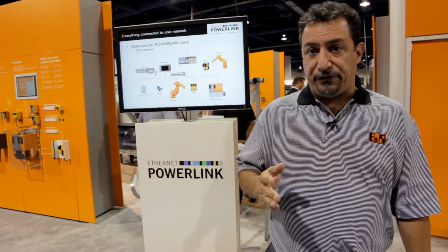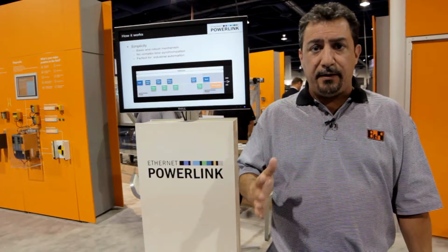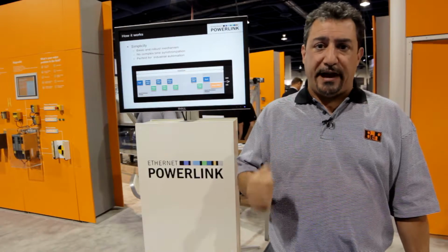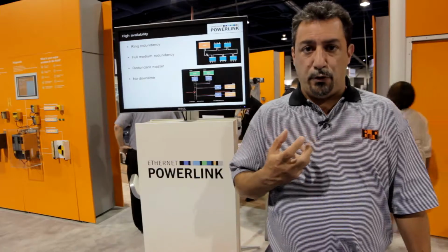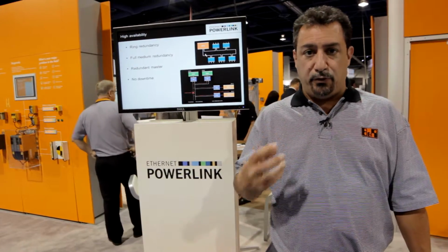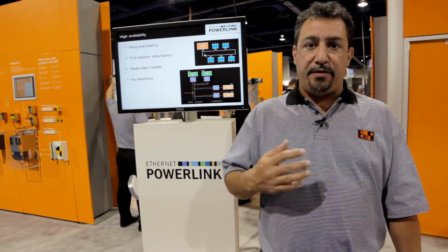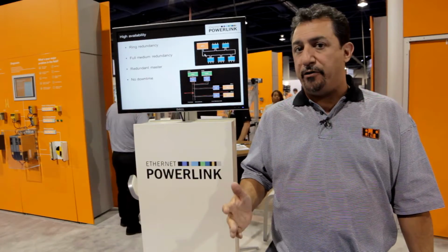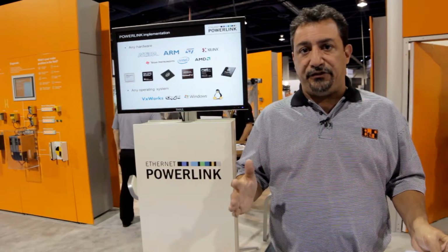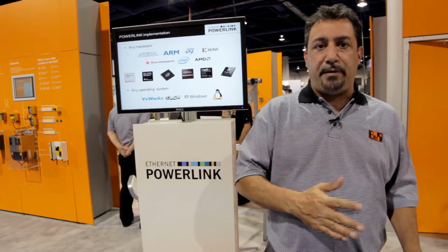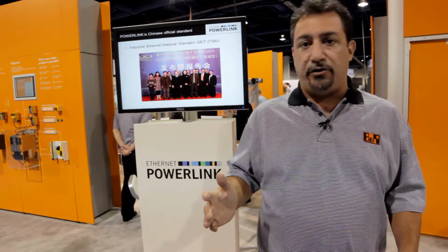The second part of the cycle is where any component can speak, and at that point you can use standard TCP/IP or SNMP or any other protocol. So components on the network are able to publish their status, error messages, etc., that are not critical to the real-time behavior of the system. Because of this division within the cycle, you're able to get real-time behavior, and you're also able to get other data without any degradation of performance.